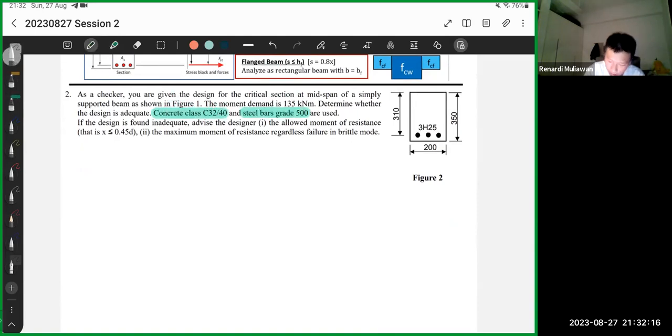So same question. So let's do it very quickly. So first step is to find the stress diagram. Again, this is just for showing. FC, FST. Then let's do FC is equal to FST because there's no compression steel. So FC is 0.567 FCK multiplied by the area.